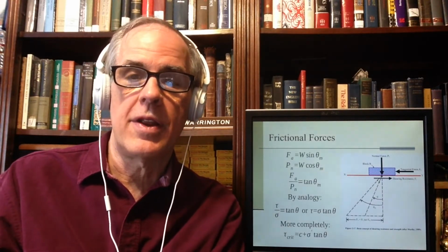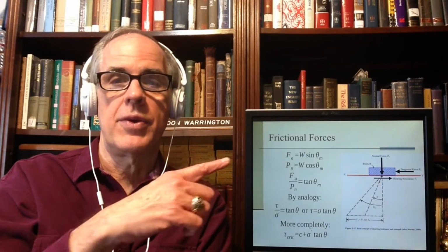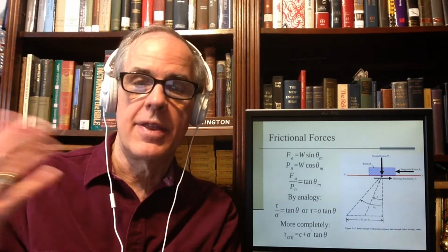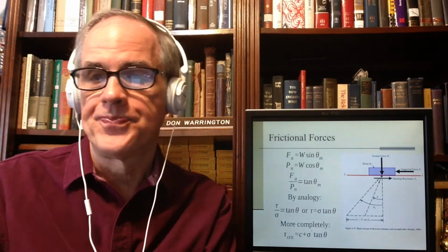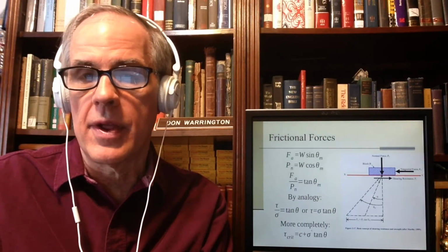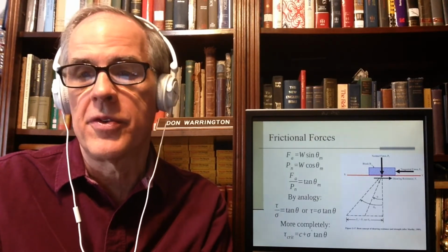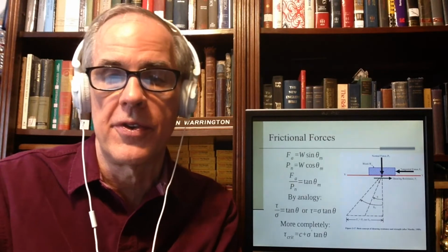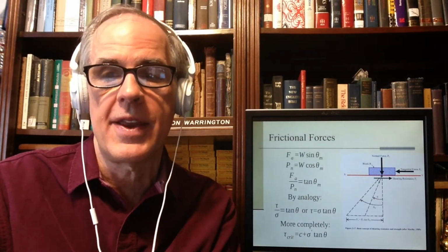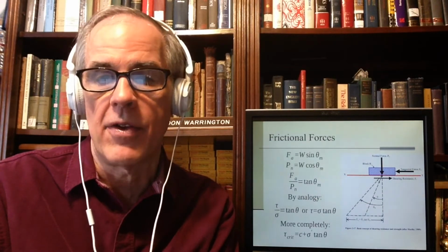And if we did a little math, using a force triangle down here, the normal force over the maximum shearing resistance is equal to the tangent of some theta m, in other words, some angle.